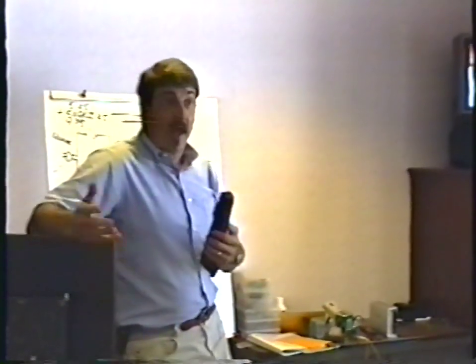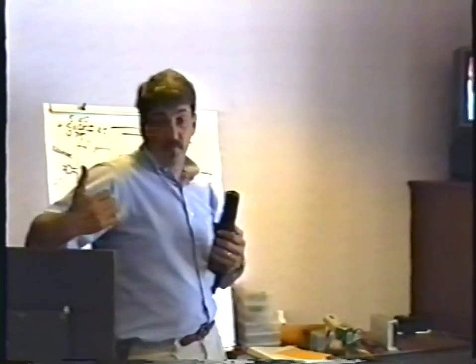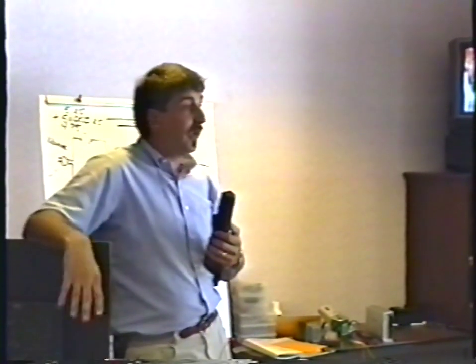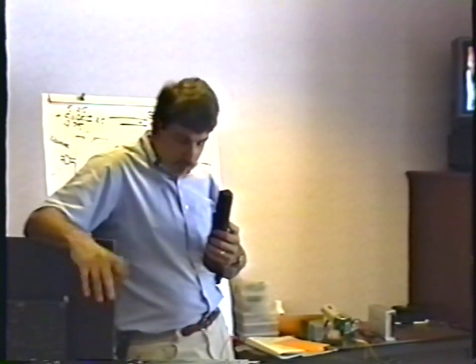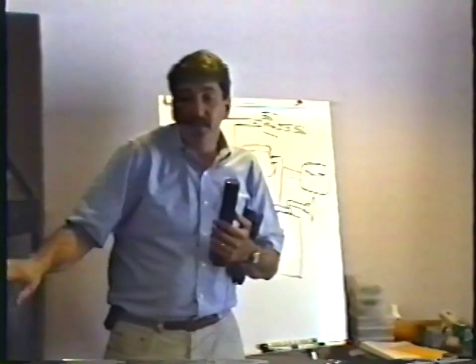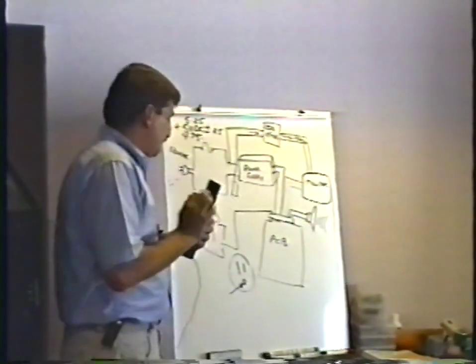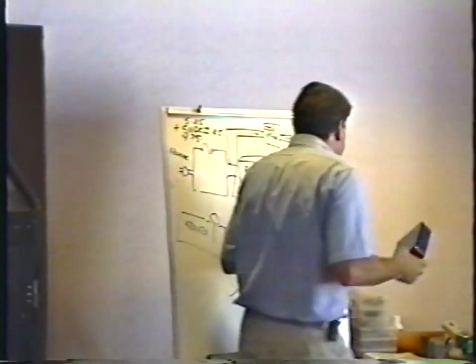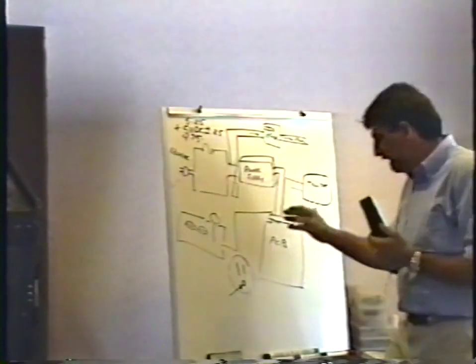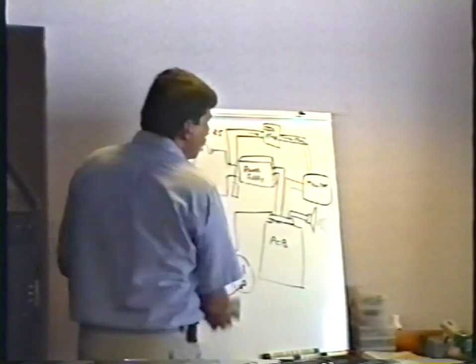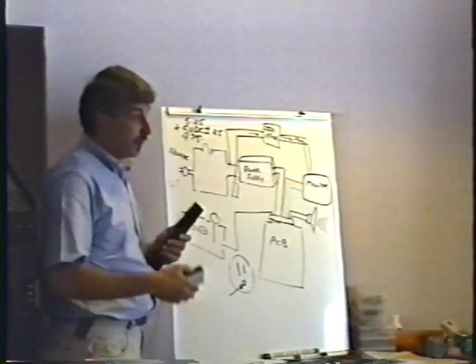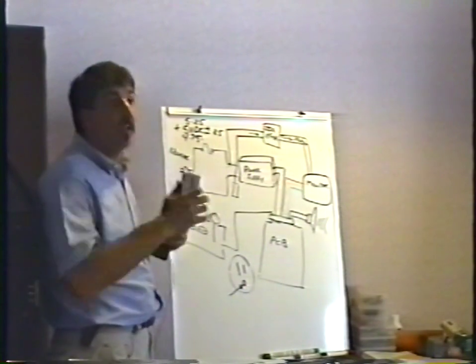Well, bullshit. Because it may work okay for a day or two, but you may be over-voltaging everything and blowing out chips eventually and so on. And speaking of chips, that's really the best place to check the 5-volt power supply. Checking it here on the JAMMA connector is really cool, if you have a JAMMA connector and you know that those pins are the pins, groovy.